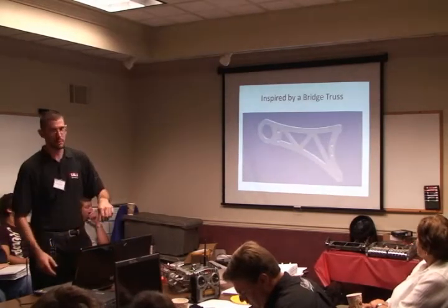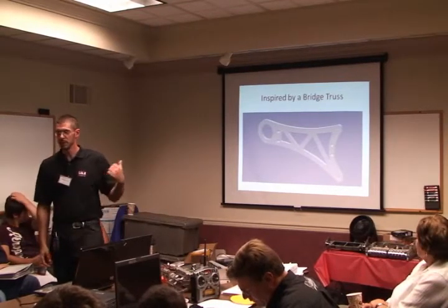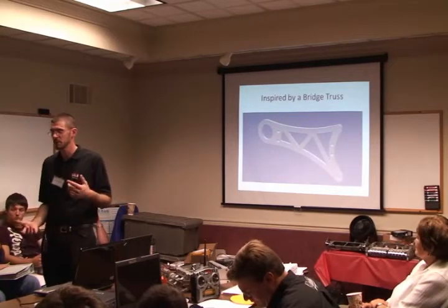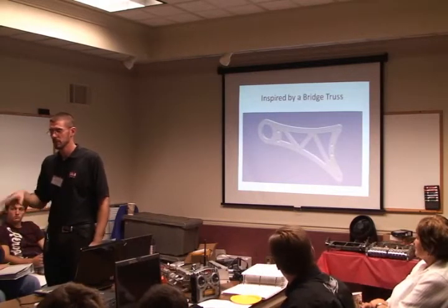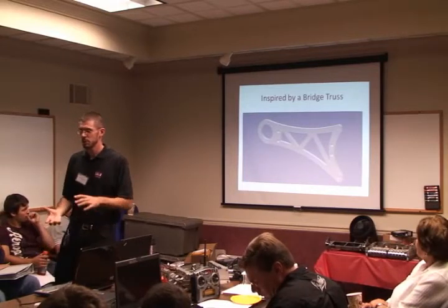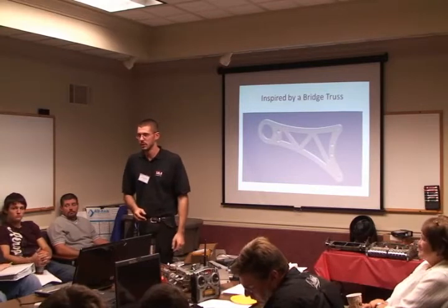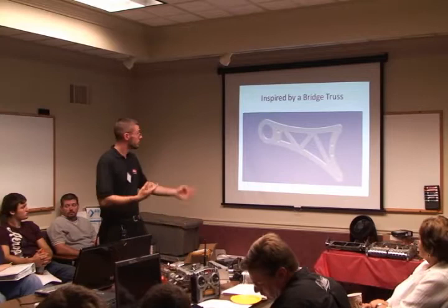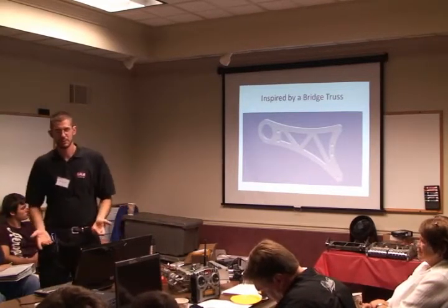And that's one of the components on his robot. It's going to be made. That's the swing arm. The motor goes through the one end, the other end attaches to the robot, and it's going to have dynamic suspension. We'll be able to raise and lower the robot, kind of like a low-rider car. So whenever it sees something in front of it, it'll be able to raise itself up and go over. Could have about 11 inches of travel from low position to high position. So it will be rather interesting. But we got the idea for that design from a bridge truss.